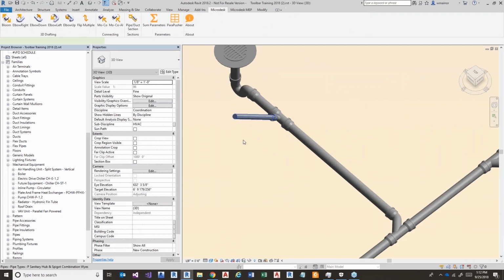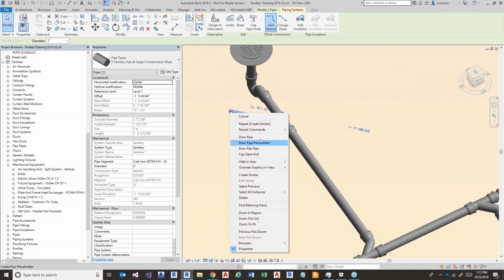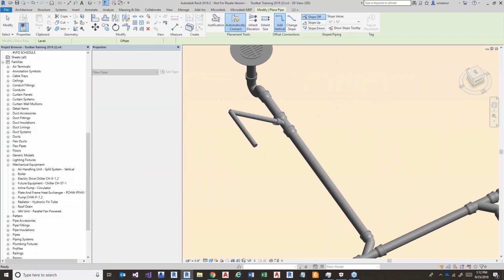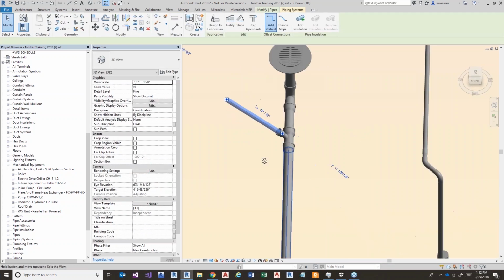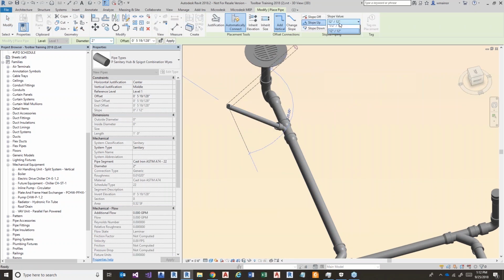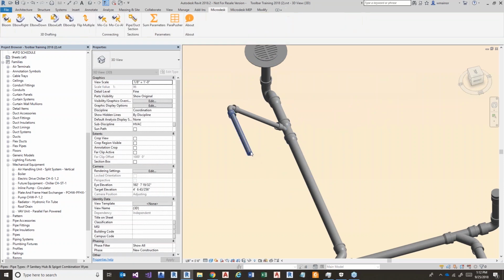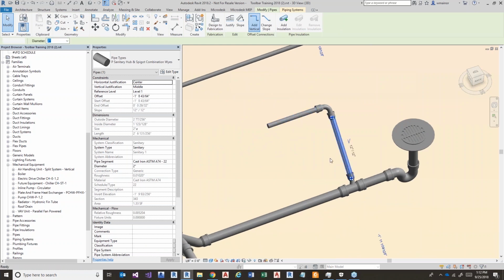And draw pipe. In this case, I'm getting an error message from my elbow. So we're coming in at a 12-inch, 12-inch. Draw pipe. If we're sloping up at it, there we go. We'll give it a slope like we probably should. And then what I could do is delete this out.